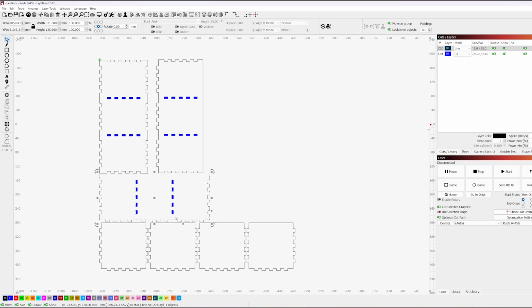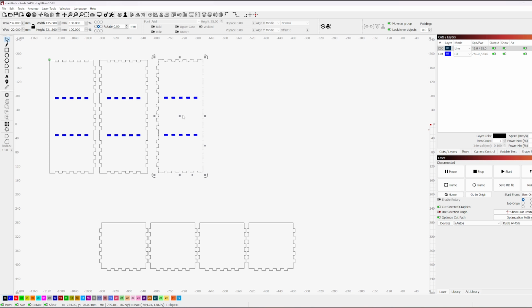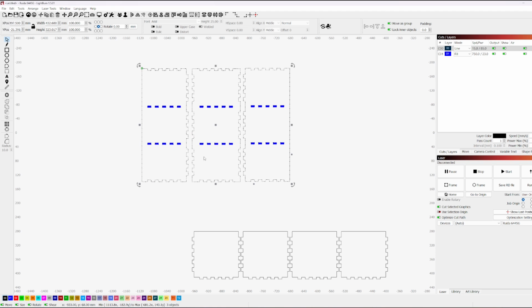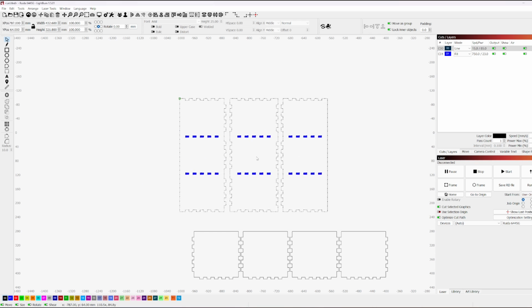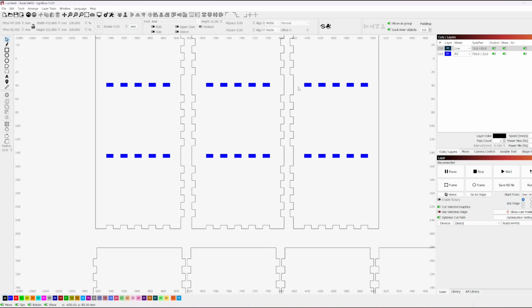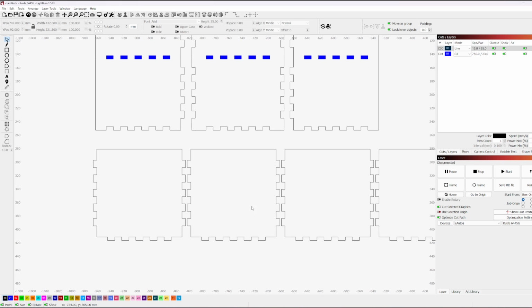Grab from the right to the left, group it, hit the decimal, and drag it up here. And we'll bring this in just a little bit more. And I'm going to highlight all 3 of these, and we're going to bottom align them and drag them over here. When we go to deal with anything with this later, we're starting off with everything on the same base point, which makes it easier to modify later.